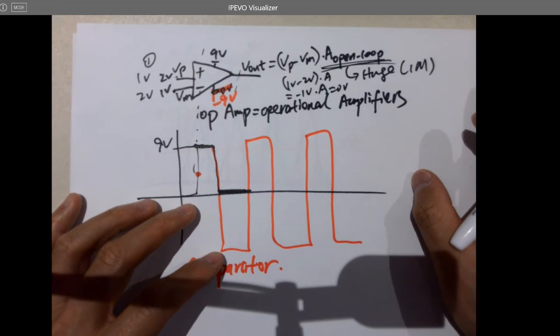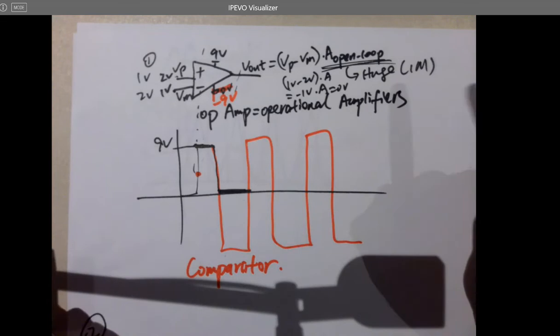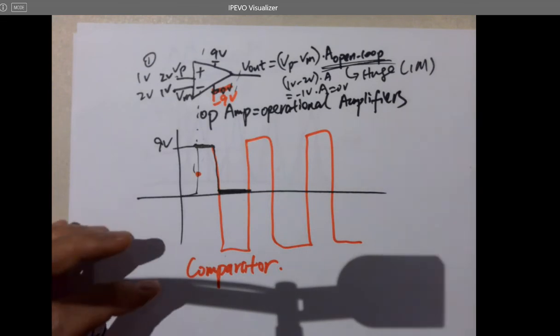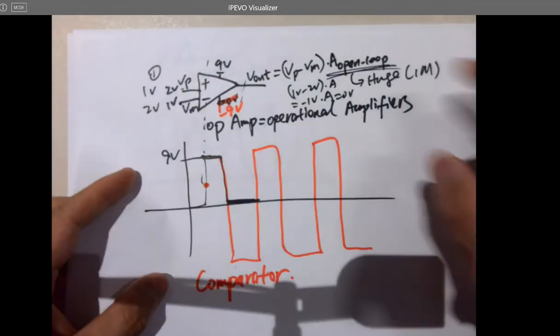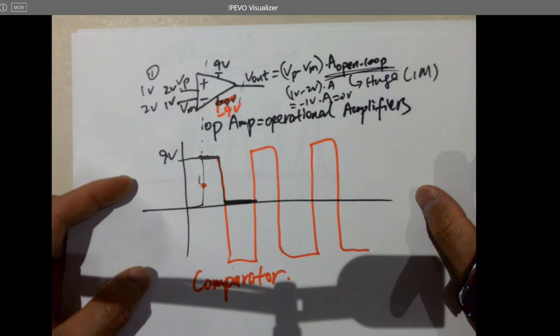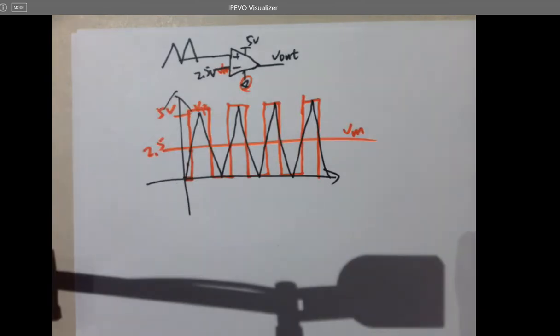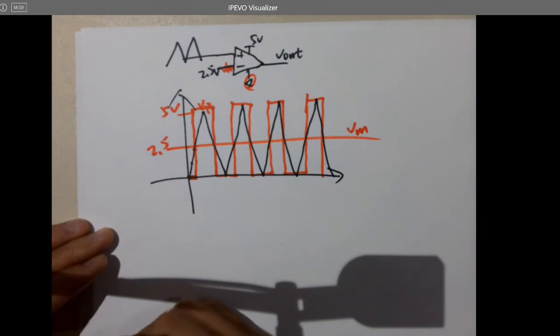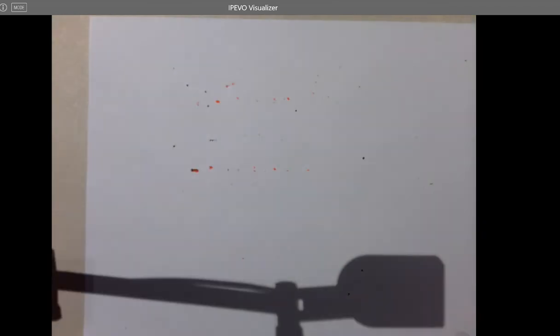So that's open loop configuration, but if you want to just amplify the signal with all the continuous different gains, you want to use a closed loop configuration, which I'm going to introduce after this. Okay. So it seems like this is really just amplify to the top and bottom rails. It seems like not really useful. So if you want to amplify the signal continuously, you want to use a closed loop configuration. So it looks different.